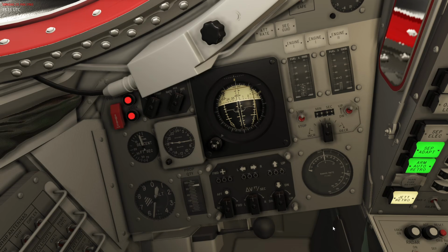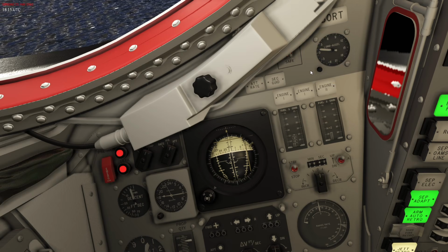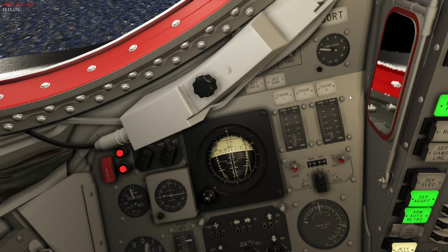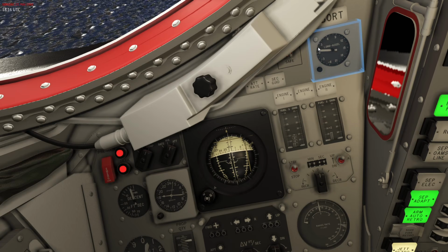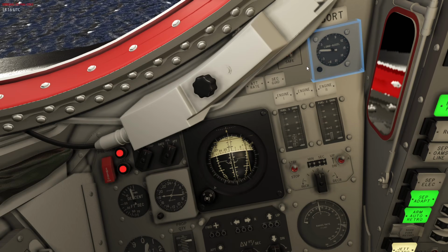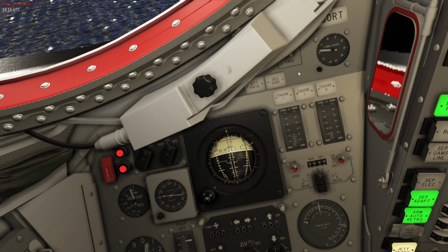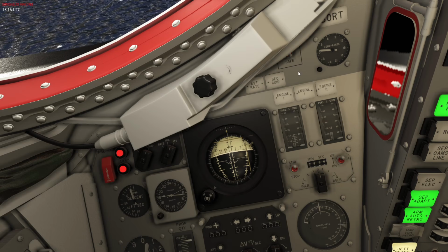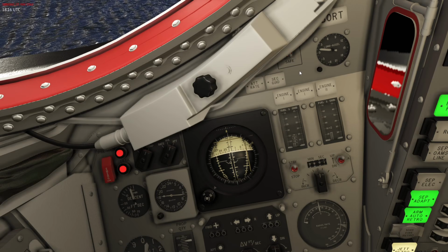So flying through the atmosphere is very much an instrumental thing. You'll need to constantly monitor your G loads, and it's always going to be quite reactive. So make sure that you don't exceed that 3-4 Gs before you do the roll maneuver, or roll reversal is what they typically call it, to direct that lift vector upwards again.